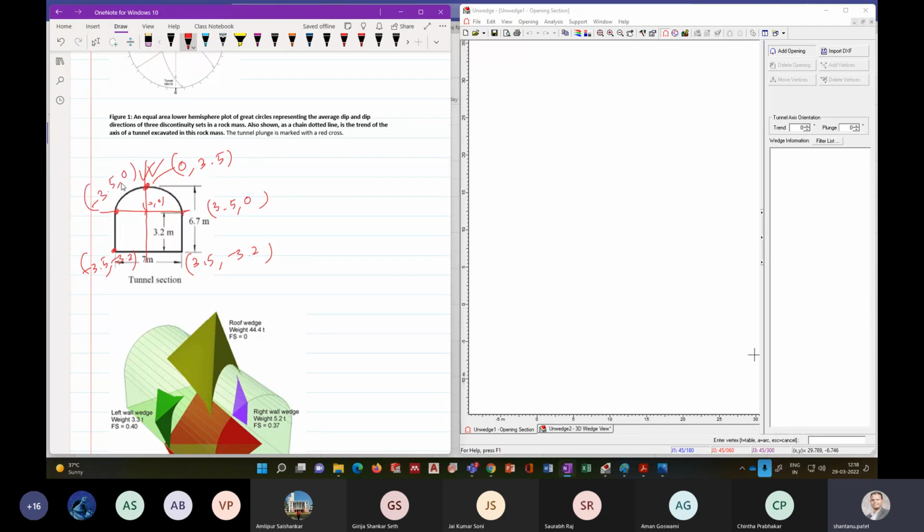So let's make this here. First point, you can type it, let's start from this corner here. So this is minus 3.5 comma minus 3.2. Press enter. Next point is 3.5 comma minus 3.2. Next point is 3.5 comma 0.